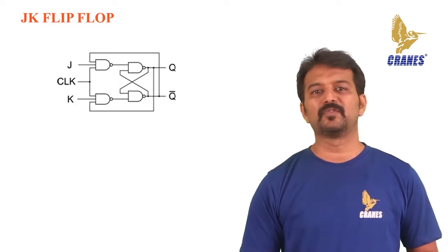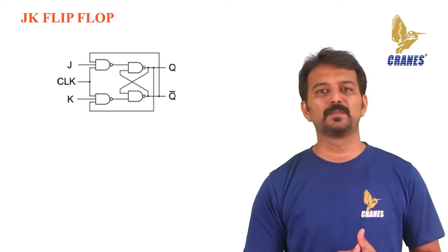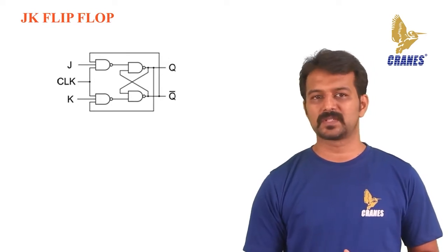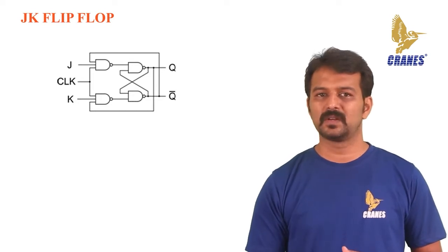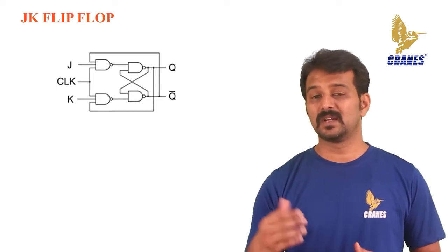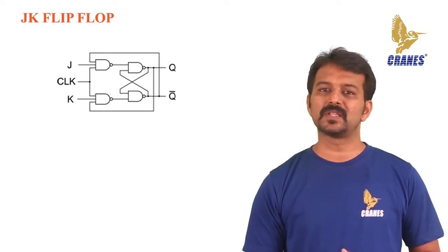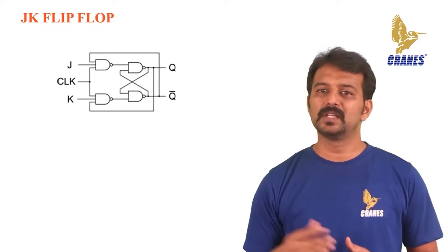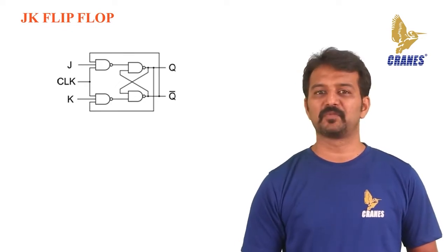Similarly, output Q' of the flip-flop is given as feedback to the input of the AND gate along with the other inputs like J and the clock pulse. So, the output becomes set when the value of the clock pulse is 1, only if the value of Q' was earlier 1. The output may be repeated in transitions once they have been complemented for J and K equal to 1 because of the feedback connection in the JK flip-flop.